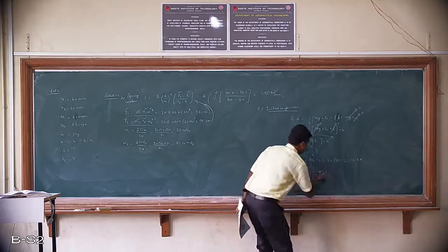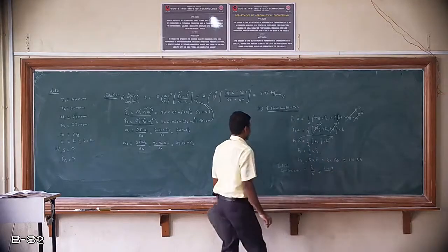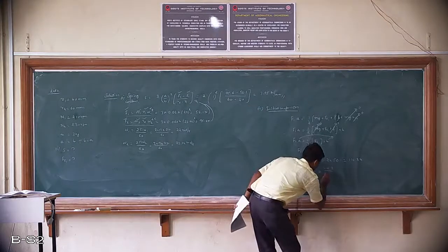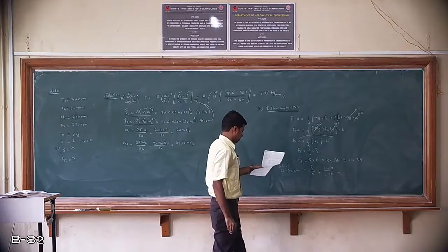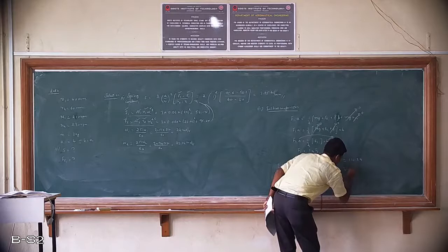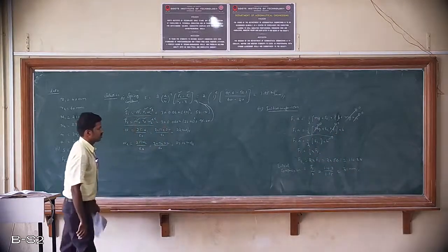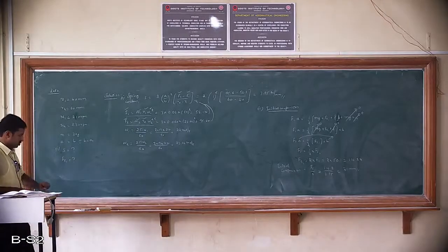We have the value for Fs1, that is 116.2, divided by the value for S, that is 3.75. So I can calculate, and the final value for initial compression is 31 mm. So this completes the problem and also the solution for the second question, that is to find out the initial compression.